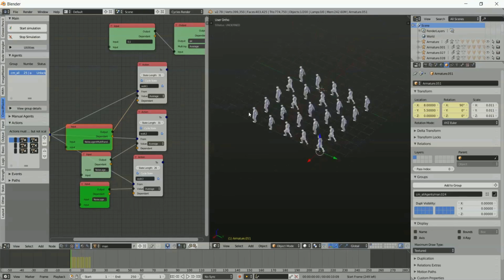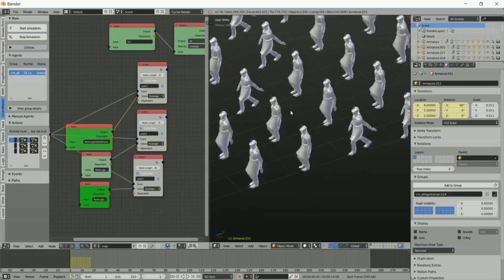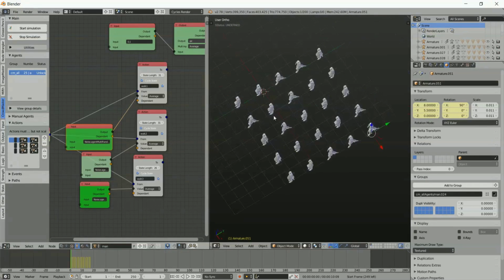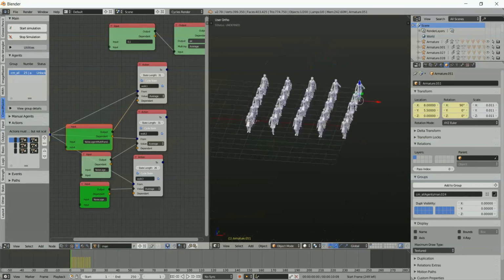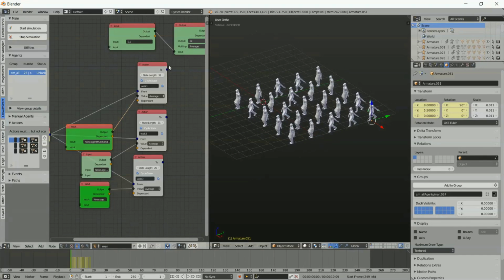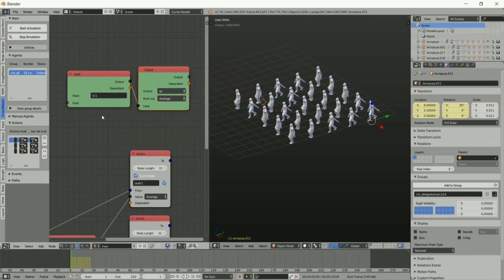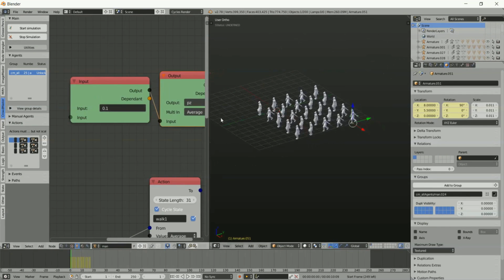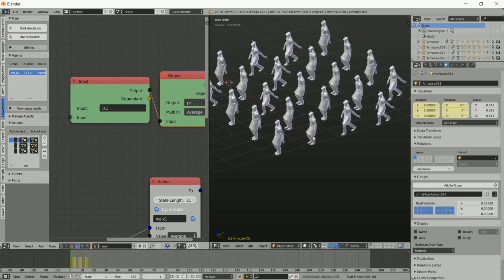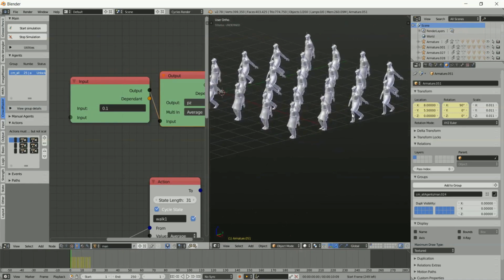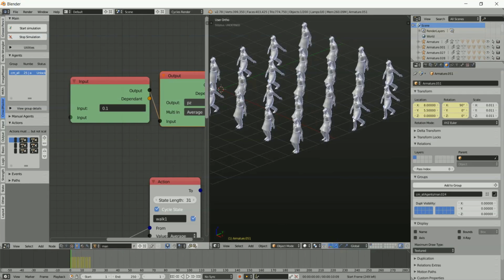So really, that's the main part of getting these agents up and walking. Again, we used formation positioning for this example, but you could use any positioning at all. Currently, like I said, this is the simplest form. This is just saying move a value of 0.1 along the local forward axis for each one of these agents. So, if you were doing some sort of random positioning where they were rotated at different angles or whatever, they would be walking through each other. But if you're doing a background crowd and you just need something really quick, this works.